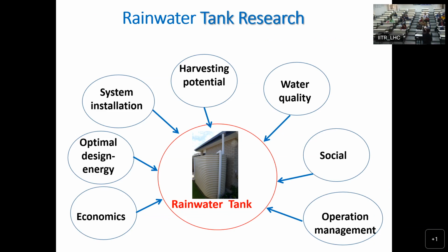Yesterday, Professor Yar talked about that IS code, and he said it is a very good document. But I would like to say one more thing when you are looking at those documents. He talked about a 20 square meter roof area, and if the rainfall is 800 millimeter, the code gives something around 64 meter cube per year. Is that right? Yes. So how was this derived?